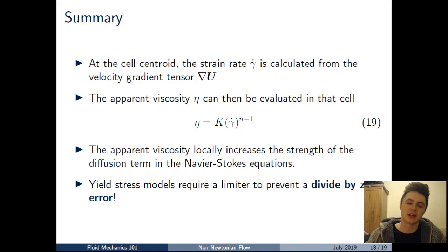And then that apparent viscosity there is going to be increasing the strength of the diffusion term in the Navier-Stokes equations, and that's how the non-Newtonian flow behavior enters the Navier-Stokes equations there for the CFD solver.